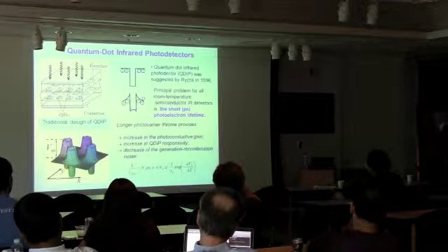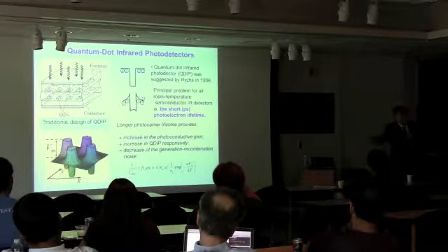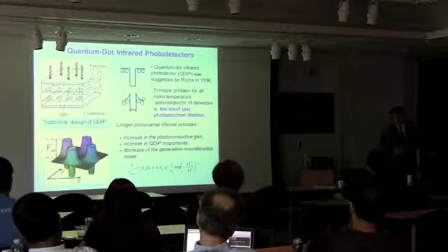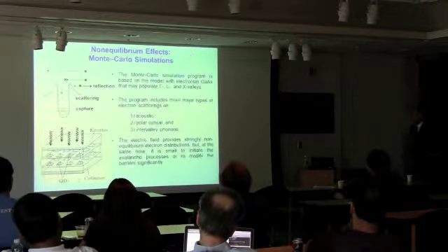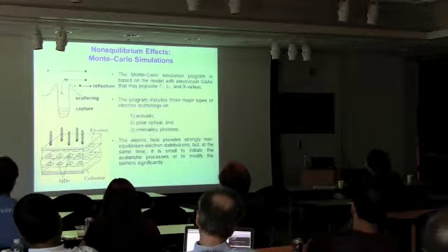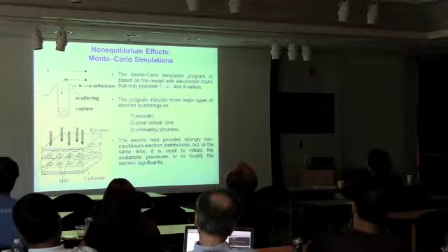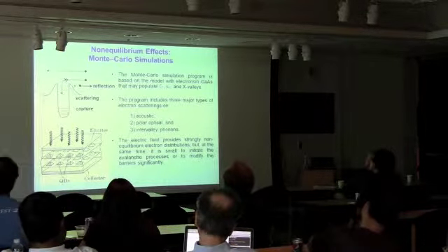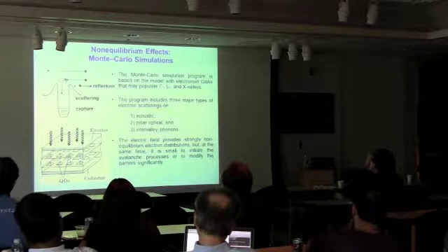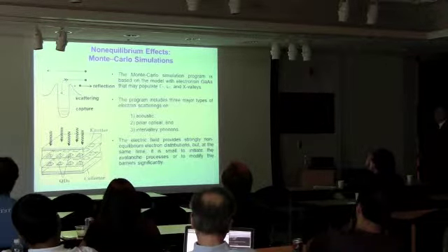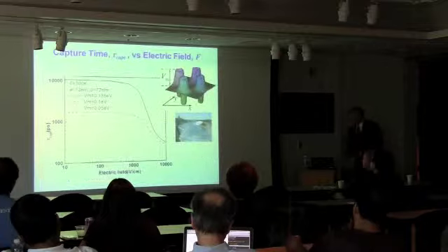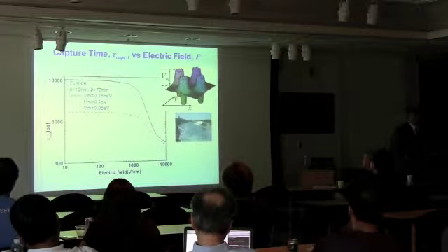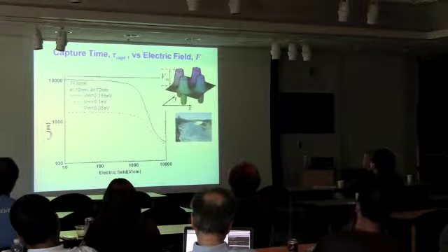the barrier height. How do we control the barrier height? By the doping that is outside of the dot. So now we go fast to the proof. So this is the detector. The popular thing to do, we did Monte Carlo simulation. We took into account everything we can, like all scattering mechanisms, and simulated what will be the lifetime of the carriers in the material depending on the doping that controls the barrier height.